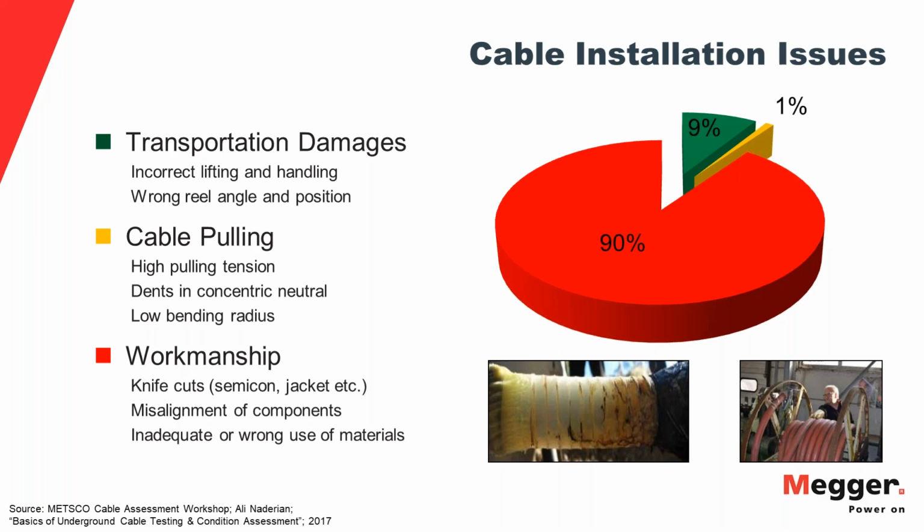So there is even a strongly preferred way of storing the drums before you go out, before you go into the trenches and pull the cables. If you store the drums the wrong way in your yard, then you're setting yourself up for failure. Another thing: when you store the drums, I can only appeal to you, always put end caps on.